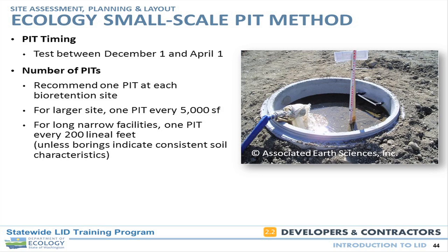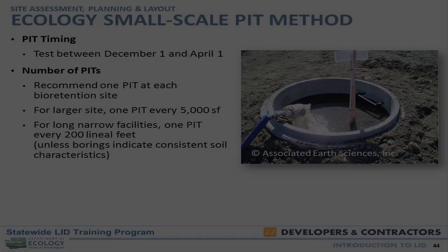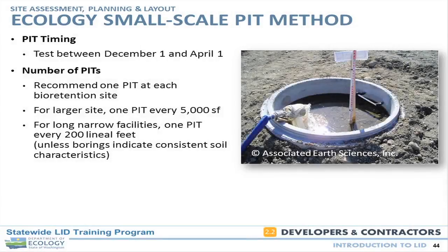These typically are all-day tests requiring a water truck and a technician. You can see there, for a larger site, we're talking about one every 5,000 square feet or so. And then for building facilities along a roadside, one every 200 feet. These are just guidelines to give you a sense of how many of these tests are necessary to complete design.